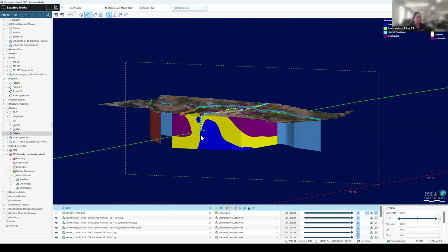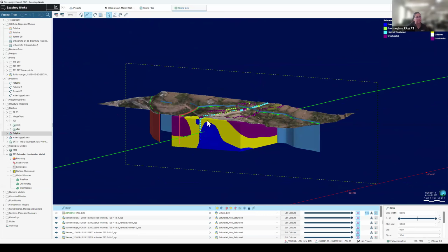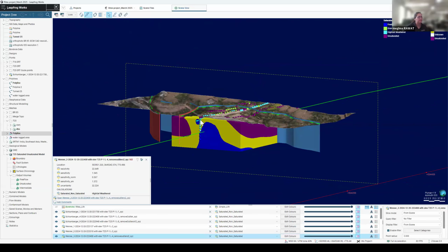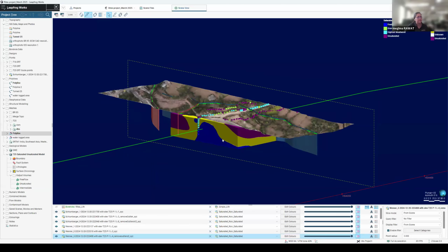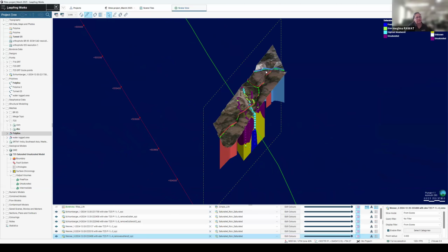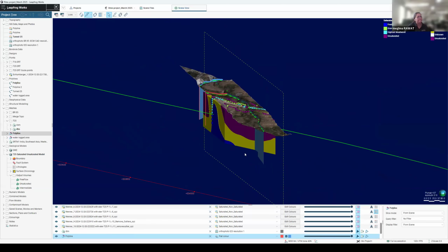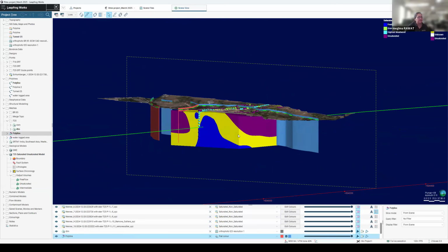And this ERT profile is also giving the same information, which is this one. So these are also highly saturated zones, cross-checked by the ERT profiles. We can cross-check our ERT data with the help of any topographical features we have. Here we can see the water table going upward. It must definitely be related to this nala, which is flowing here and coming right across our tunnel. So this is our tunnel.